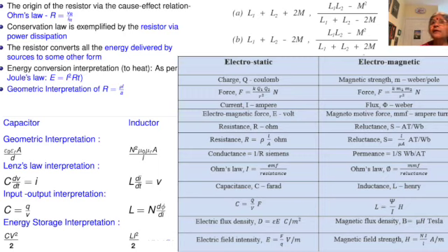On the other hand, when the fluxes are opposing each other, the total inductance is actually reduced, because we have (L1 L2 minus m square) divided by a larger quantity as given by L1 plus L2 plus 2m. So these are important formulae that had better be remembered, and the problems addressed accordingly, because it throws light on the workings of these connected together.